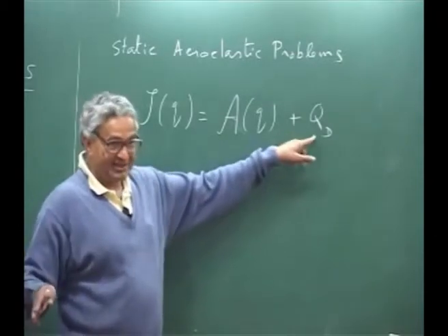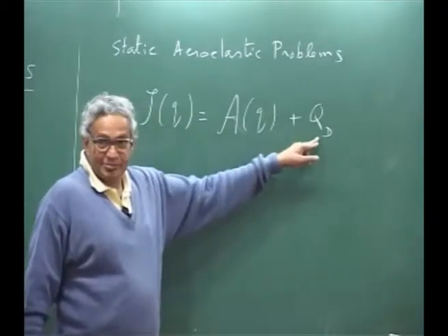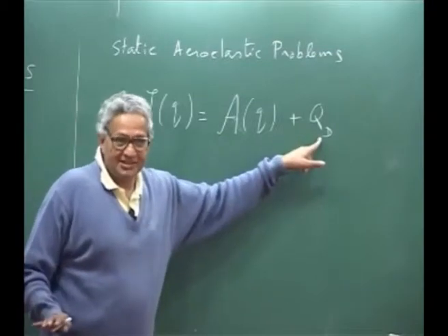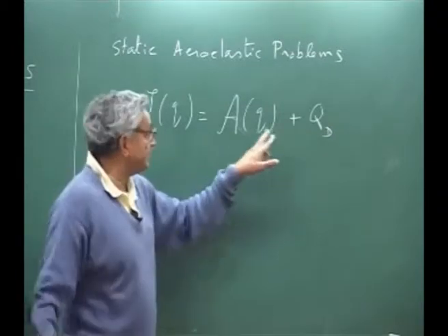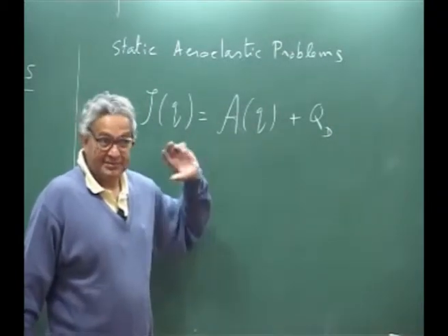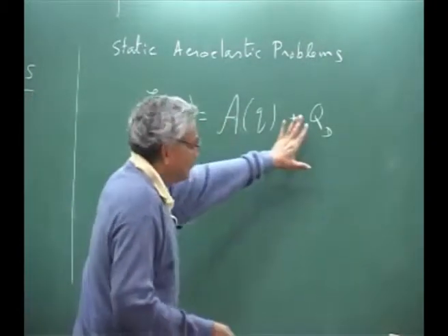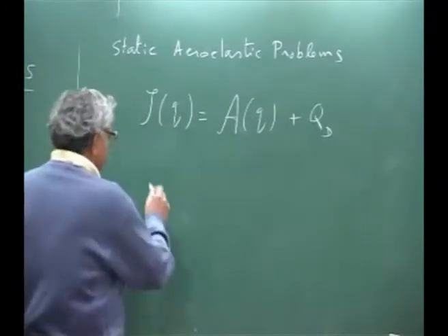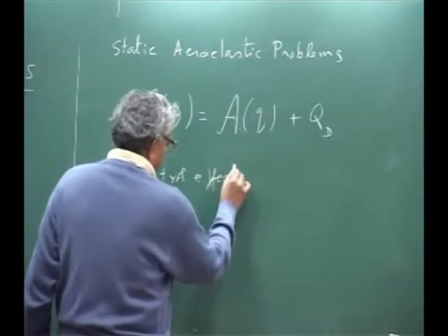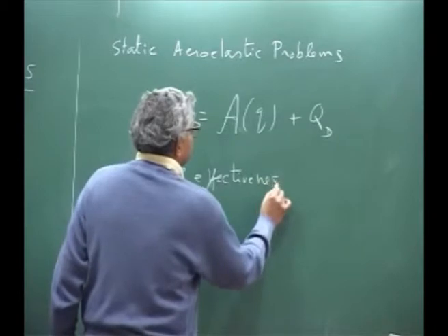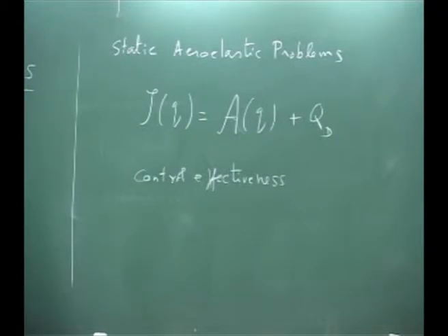That is why I put a D here, even though I put it as a dynamic load earlier. This situation can be due to control surface motion, which is independent of the generalized coordinate of the wing deformation. This type of problem is basically control effectiveness, and control reversal, etc. They will come. You understand?